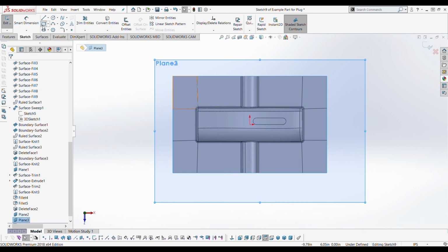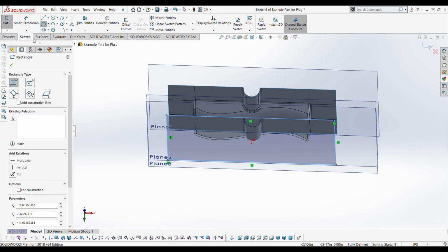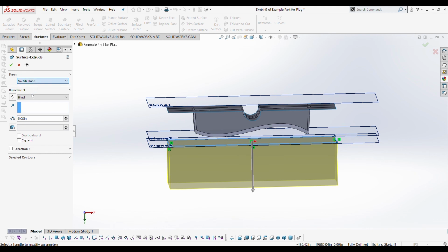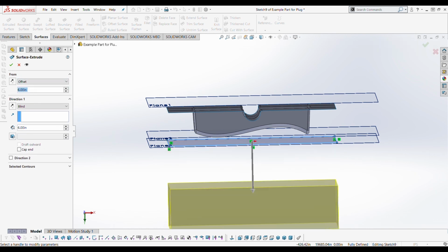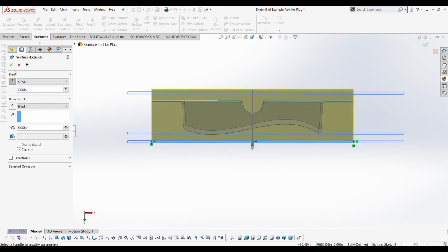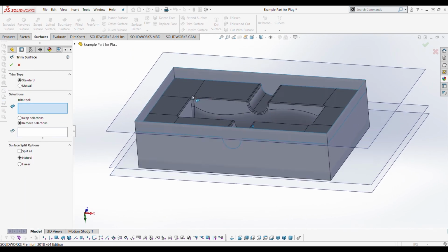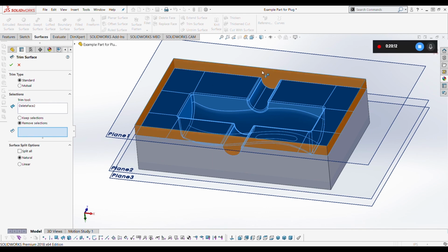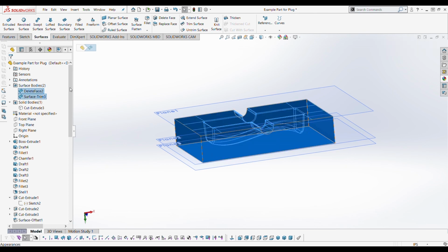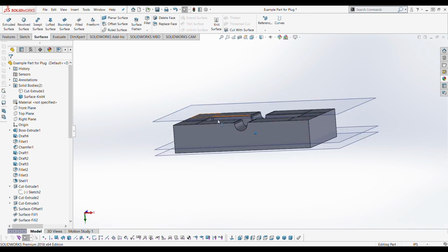We'll do the same thing we did last time, sketch ourselves a rectangle edge to edge of our flange and do a surface extrude. Doing the same trick as last time, we'll offset it by those 6 inches in the other direction, have it come back down to 6 inches, and we'll put the end cap on. And finally trim the surface using our flange again and removing the excess from the top, and do a final knit to create a solid.